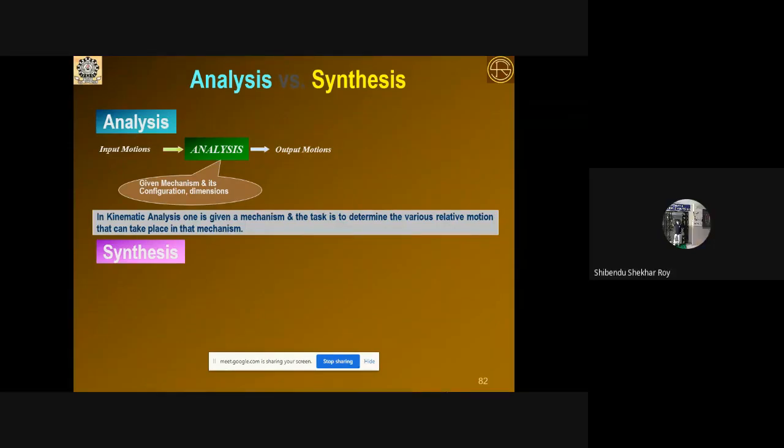Okay, rack and pinion is a good mechanism which converts the rotary motion of the pinion. That means the motor is attached to the pinion and drives it, and once the pinion rotates, the rack will translate, and the tray is fixed to the rack. So this is a very well-known mechanism in the DVD writer of a particular company.